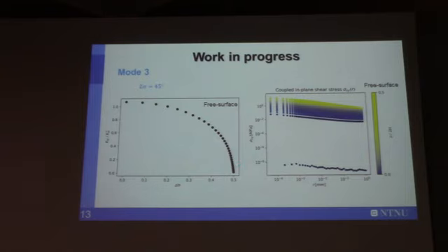So we obtain the stress intensity factor in mode 3, and we see how it decreases along the notch front. Here we have the coupled in-plane shear stress, that is the stress induced by an anti-plane loading of the plate. And you can see how, approaching the free surface, the stress field increases. And this is in agreement with what's been predicted by previous researchers.